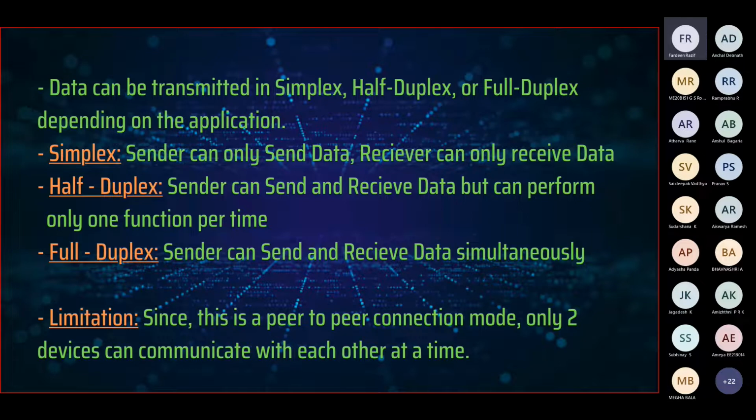And the one major problem with this UART communication is that it's peer-to-peer. Like at a time, only two devices will communicate with each other. You can't communicate with multiple devices using UART. That's the main drawback. And now let's see how we can overcome this drawback using another mode of communication called